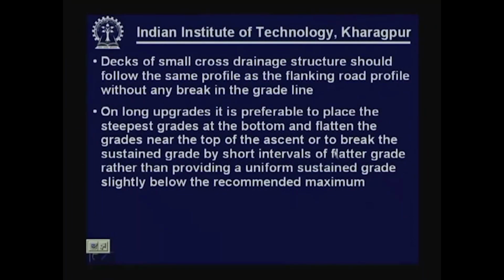On long upgrades, it is preferable to place the steepest grade on the bottom and flatten the grades near the top of the ascent, or to break the sustained grade by short intervals of flatter grade rather than providing a uniform sustained grade slightly below the recommended maximum. This is just to provide a relief to the traffic, continuously negotiating a steep grade. So, instead of that, provide a steep grade, give a relief, then again provide a bit steep grade, provide a relief, so that operation becomes more easy and more comfortable for the commercial vehicles or heavily loaded vehicles.